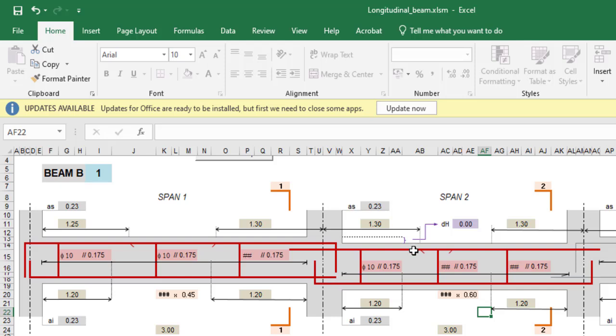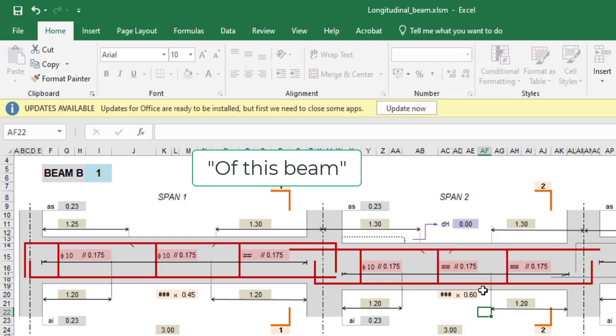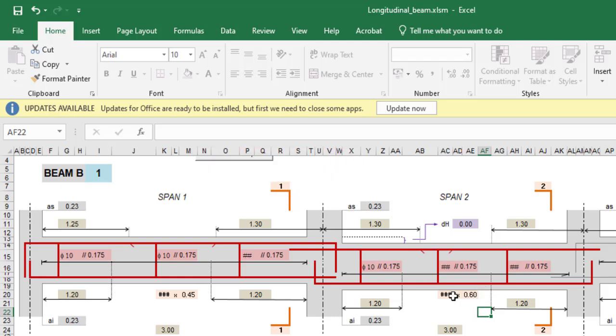Do you want it to be distributed to the top or to the bottom? Let's say, for example, you want the top of all of the beams to be flush. That means your DH will be equal to 0. Then the 150 mm difference will be added to the bottom of this column. So you can see that the bottom here will be deeper, but the top of the beam will be level. That is how you work with DH.